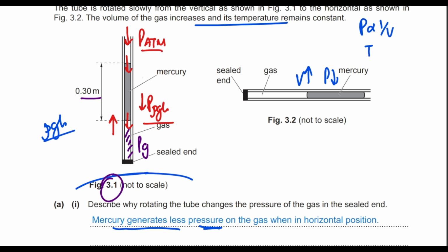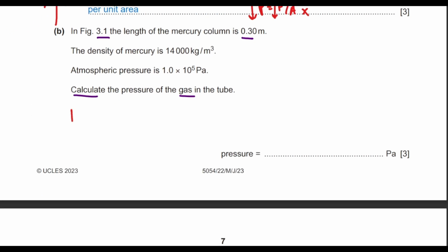They are trying to compress it, but the gas is holding on its own. It's holding both of these two pressures or forces on its own alone. So we can say that the pressure of gas is equal, because it is good enough to stop them from moving, to the pressure of atmosphere plus the pressure of mercury, which is rho gh, right?